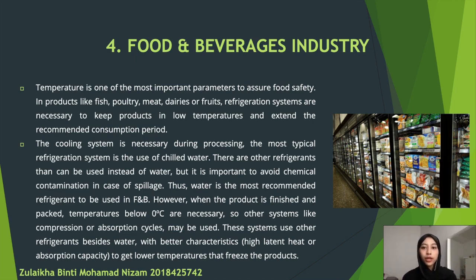However, when the product is finished and packed, temperatures below 0 degrees Celsius are necessary, so other systems like compression or absorption cycles may be used. These systems use other refrigerants besides water, with better characteristics such as high latent heat or absorption capacity to get lower temperatures that freeze the product.